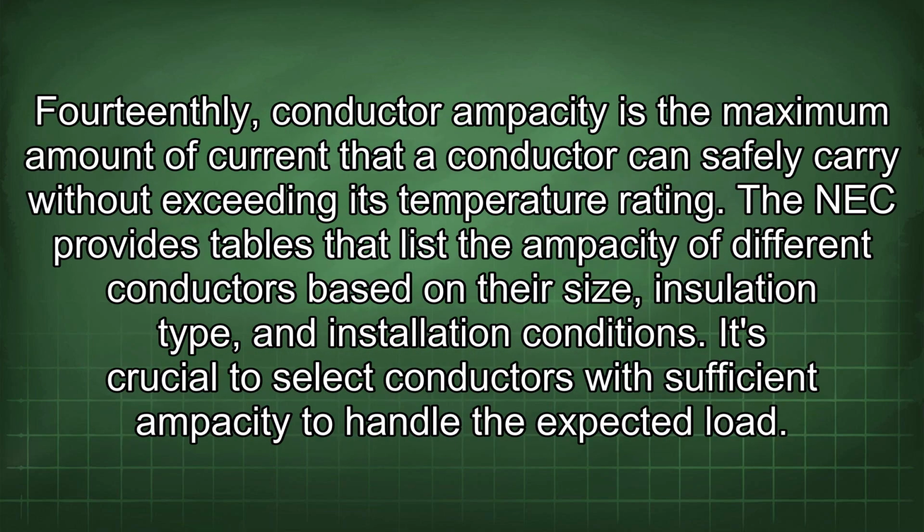14thly, conductor ampacity is the maximum amount of current that a conductor can safely carry without exceeding its temperature rating. The NEC provides tables that list the ampacity of different conductors based on their size, insulation type, and installation conditions. It's crucial to select conductors with sufficient ampacity to handle the expected load.